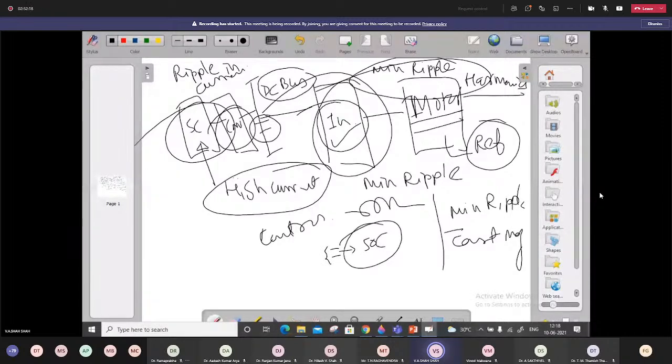But of course, as time goes on, the terminal voltage of the supercapacitor decreases when it is in discharging mode. For a small period of time, that is a delta T, you can assume that the supercapacitor voltage is constant. So when you develop your small signal model, for that particular point only, you can assume that the supercapacitor voltage is constant, but not as a whole. That is the reason why we prefer to supply it with the converter.